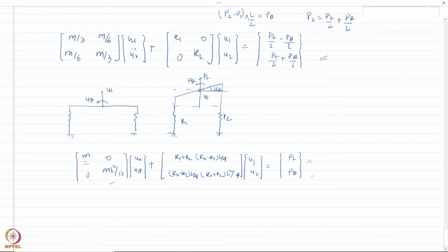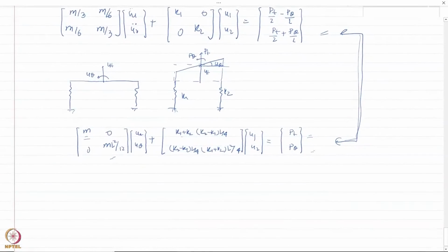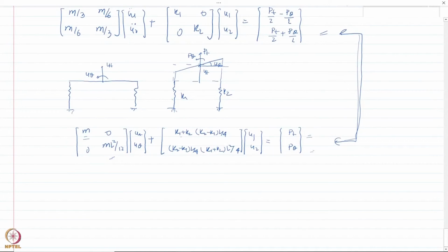Now you might see a different formulation of the equation of motion, but we'll see that in the next chapter. A dynamic system is basically defined through its modes, shapes, and frequencies, which are called modal properties. So even if these equations are in a different form, basically they represent the same system, because through some mathematical manipulation this can be transformed to this, or this can be transformed to this. We use a matrix called a transformation matrix to do that, and let us quickly see how we do that.